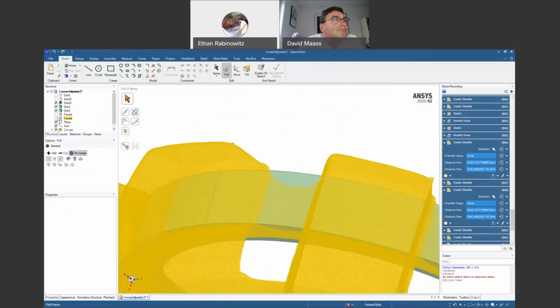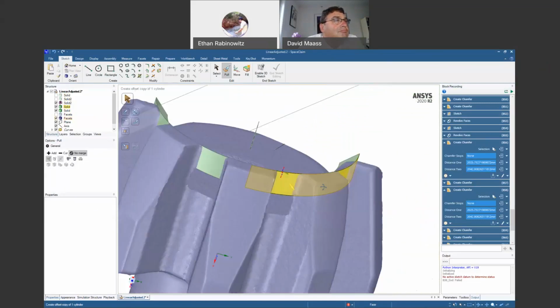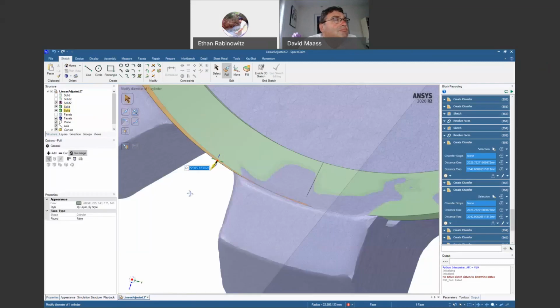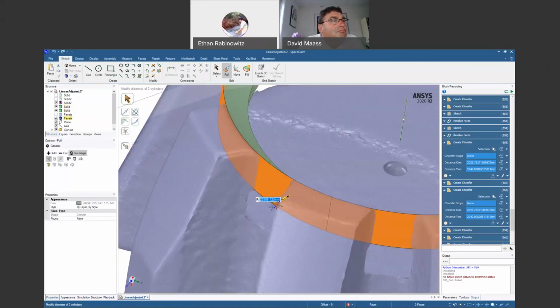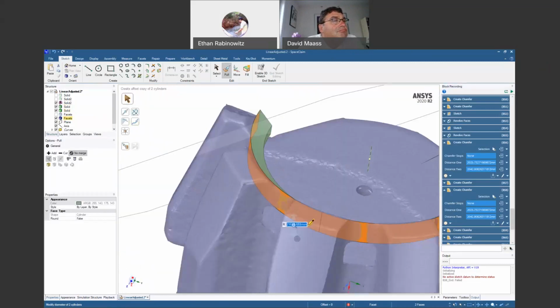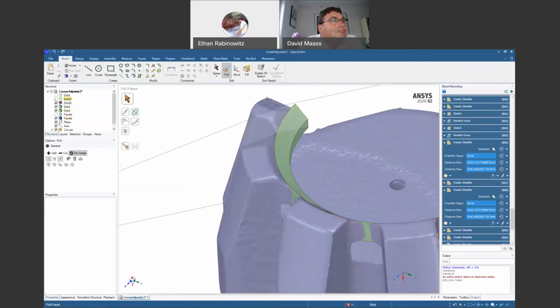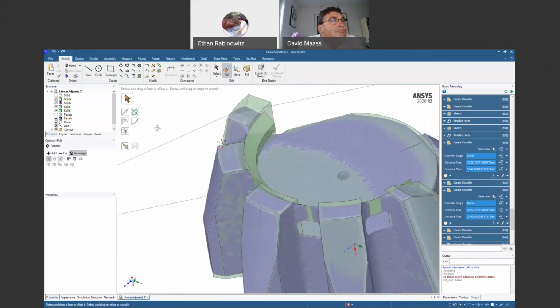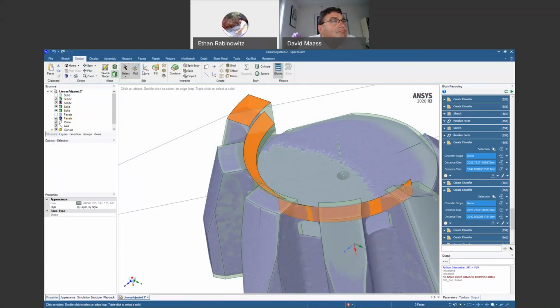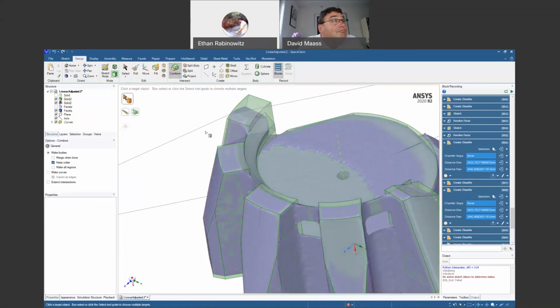And all I really want to do right now is adjust where this back face is. So it's really these two at the moment. And I could either drag or I could just do an up to and grab that facet in there. That looks good there. And see if we can merge these all together. So we'll grab a face on each: 1, 2, 3, and try to combine. We got the one solid body.